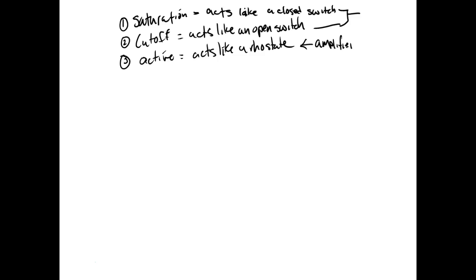You're talking about checking to see if the transistor is good or bad. I'm trying to see whether it's acting like an open switch, a closed switch, or an amplifier. So here's my transistor. If this is the emitter, and this is the collector, and of course this is the base, where is the switch at? Where's the valve at? What valve are we controlling? Between what two leads? Between the collector and the emitter.